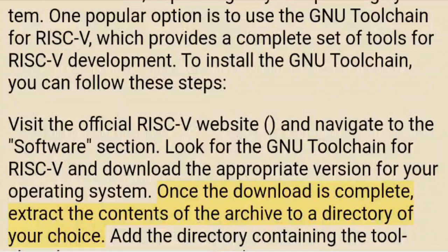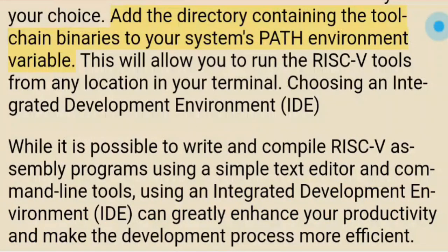Once the download is complete, extract the contents of the archive to a directory of your choice. Add the directory containing the toolchain binaries to your system's path environment variable. This will allow you to run the RISC-V tools from any location in your terminal.